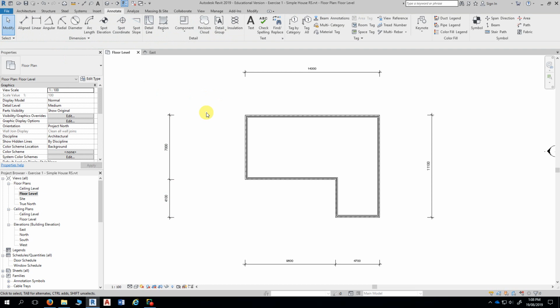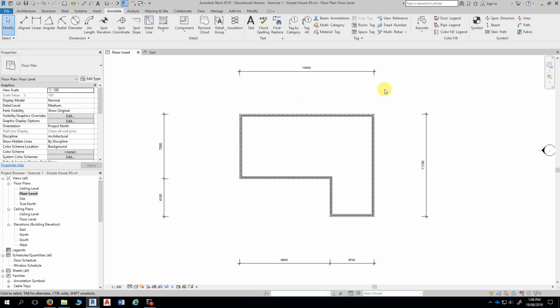So the way that we tackle this from here is to set the length of this wall here. What do we have to do? Click on the actual measurement there and then type it in? No, we don't click directly on that. To set the length of this wall, what has to change? What has to move? Either that wall or that wall has to move.